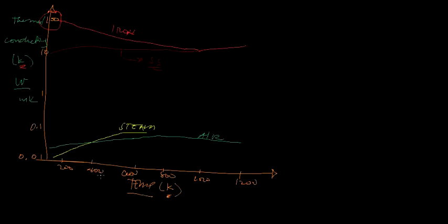Say we have, for example, a certain condition wherein we have a normal temperature and pressure. Then the value of our thermal conductivity, the value of our K, is fixed and can be found on tables. So that is for a normal temperature and pressure condition. Okay, so that's why we can use a certain constant K. Okay, for temperatures and pressures beyond, the thermal conductivity is a function of temperature and an average value for K.